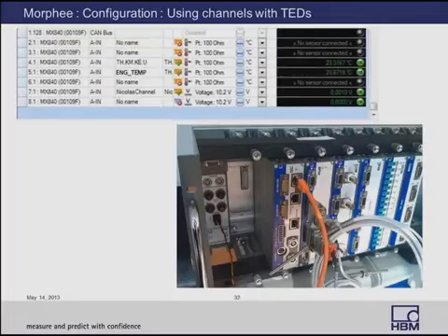Once I reconnect this sensor to a different spot, you see now in a different plug, Morphy knows how to recognize this engine temp channel, and Morphy can read now the 23.6719 temperature. So automatically, without restarting the software or without restarting the hardware, you can plug and unplug your sensors.